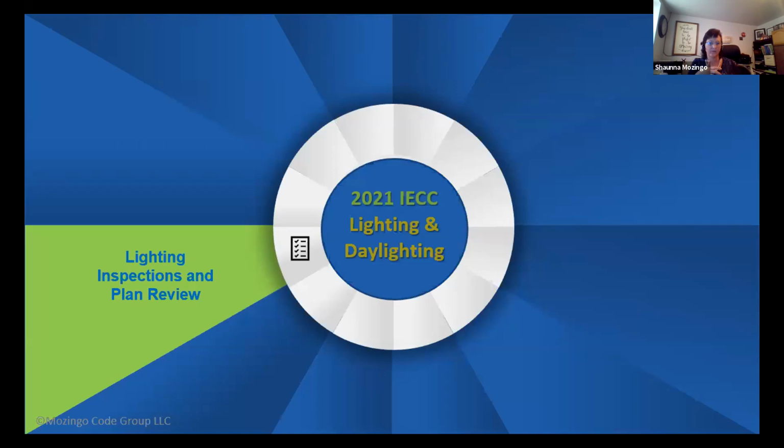That doesn't mean you can't verify lighting requirements until then, because 2021 did a good job of laying out that step-by-step way of calculating lighting loads. It's really not hard at all to sum up the amount of the lighting watts per square foot, but the burden of proof is on the designer, not the code official. So ask to see those lighting load calculations and spot check them.